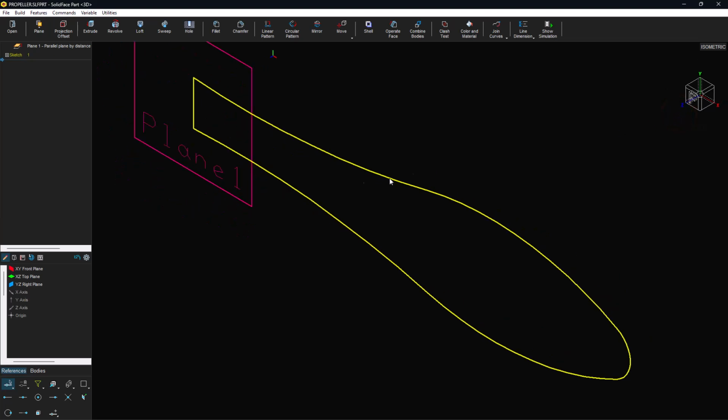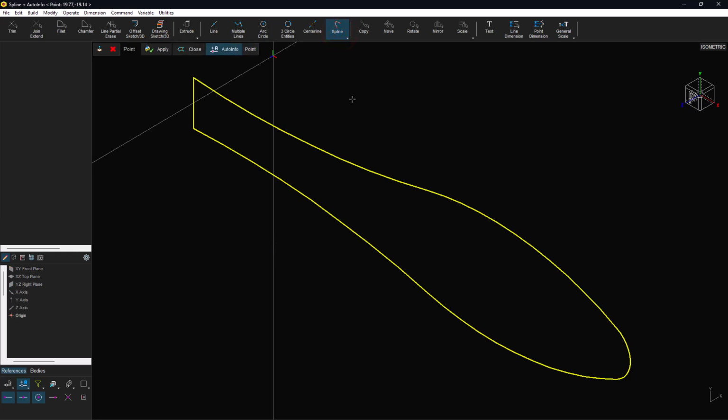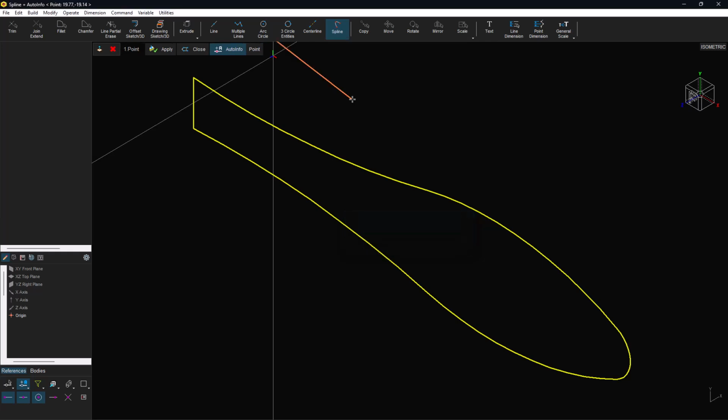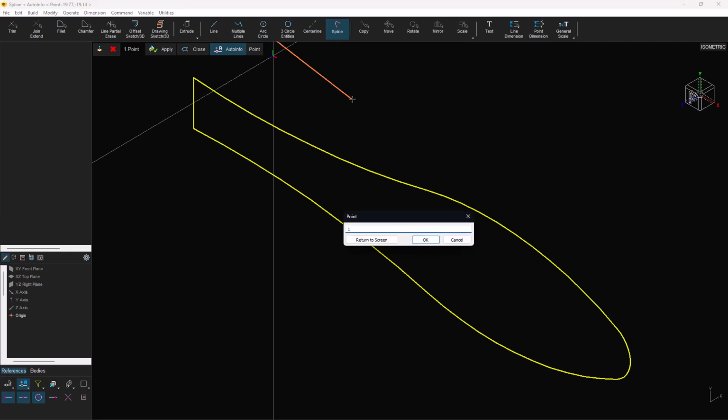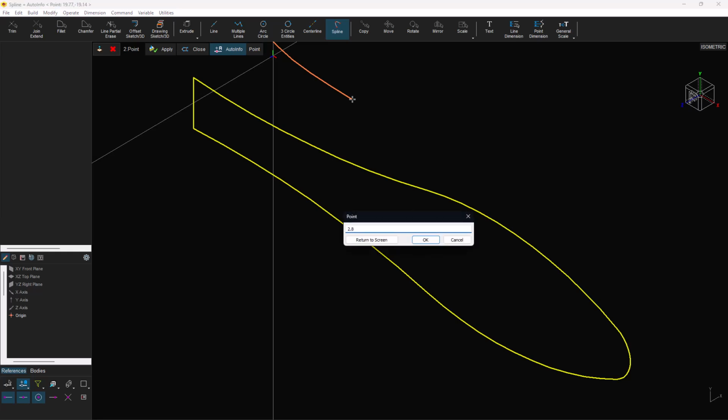Create two surfaces with splines. The propeller blade will be built between these two surfaces. Define a sketch on the YZ right reference plane, perpendicular to the blade profile plane. Define an open spline with 3 points. Point 1, -3 and 7. Point 2, 1 and 1.5. Point 3, 2.8 and 7.8.